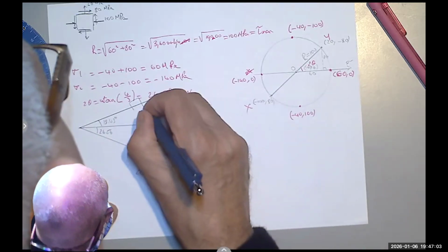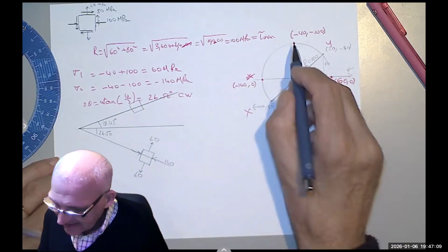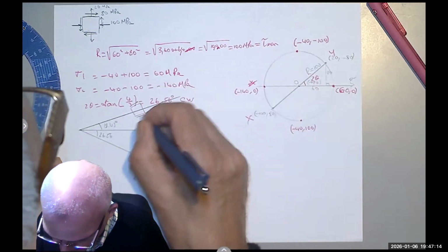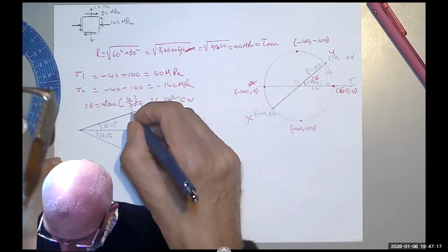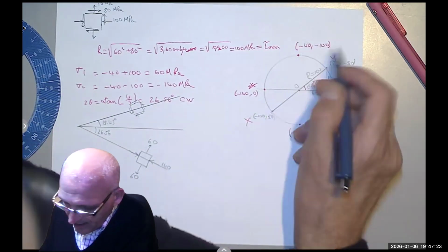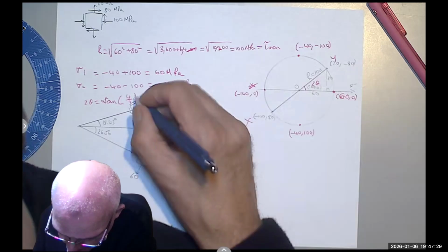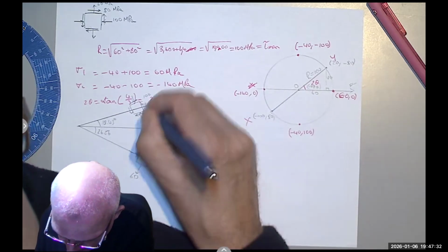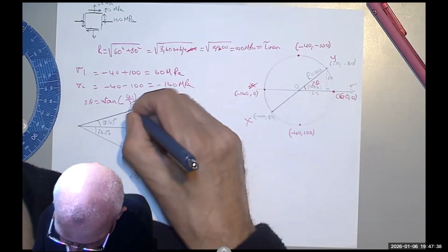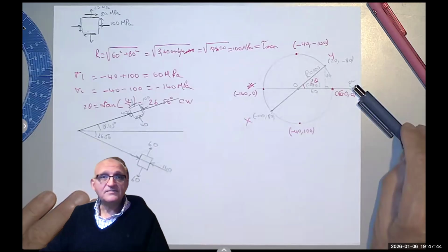However, if I decided to rotate in that direction, the y becomes the face that has negative shear, meaning going clockwise, and the x is positive or counterclockwise. And all of them have 100 for the shear and 40 compression on both faces. Oh my, my drawing is horrible. 40 compression. And that's how you do it.